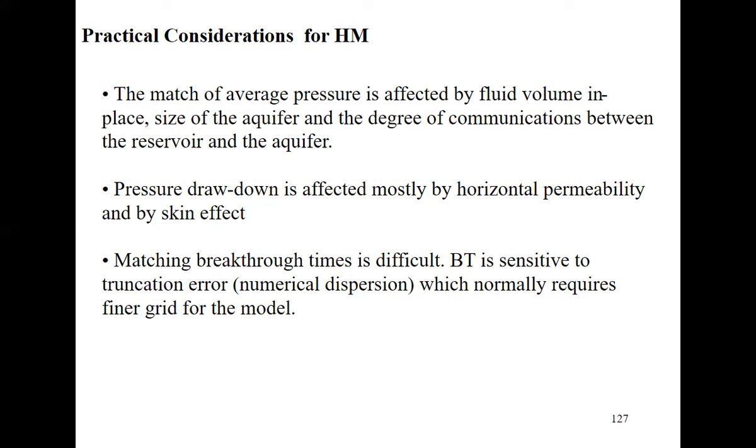Pressure drawdown is affected mostly by horizontal permeability and by skin effect. Because we know when you produce, you have this permeability. When we have high drawdown in one region, or in horizontal wells, we may have coning and water production. So I may say that the pressure is affected by high drawdown.